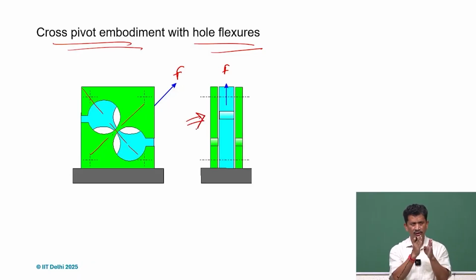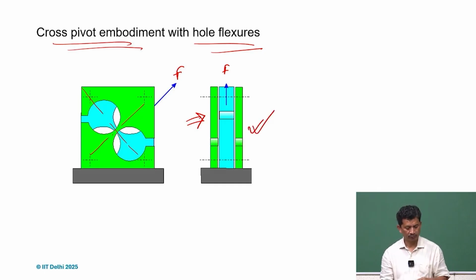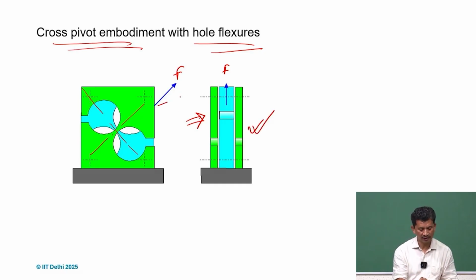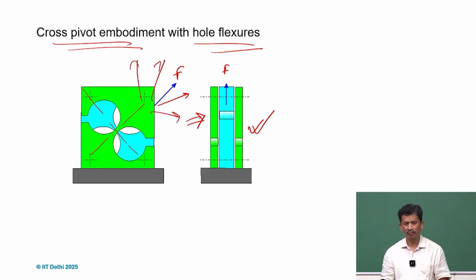We just split one of the sides into halves and put them on either side and get this sandwich structure and the symmetric design. Very good, and in this case the force direction can change in any direction. We may not have to worry because one will always take care of that load. We can write the cos and sine, resolve into two components, and it can take care of that.